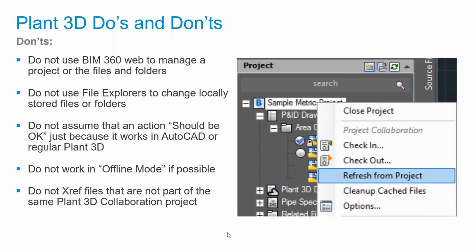And then try not to XREF files that are not part of the same Plant 3D collaboration project. That's where things can get kind of tricky if you're trying to go through Desktop Connector and attach a drawing from another project somewhere else. So just a word of caution there.